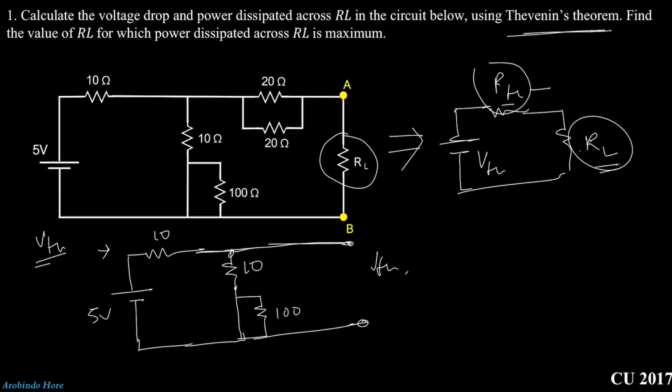Right? You understood? And then you can see here this is a short and then a resistance. Okay? That means this path is 0. When current comes to this branch, at that time current has two options. One is to flow through 0 ohm, the other through 100 ohm. What will current do? It will go with the low resistance path, that means 0 ohm. So no current will flow through the 100 ohm path. Or if I just apply the current division rule, at that time you can see I100 will be opposite resistance 0 divided by total 100 plus 0 multiplied by I, if this current is I, and this is equal to 0. That means no current will flow through the 100 ohm. Right? So what we can do? We can remove this resistance also.